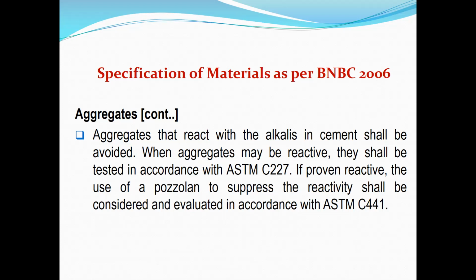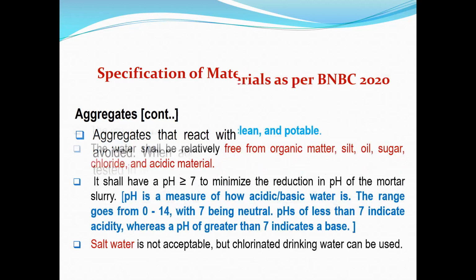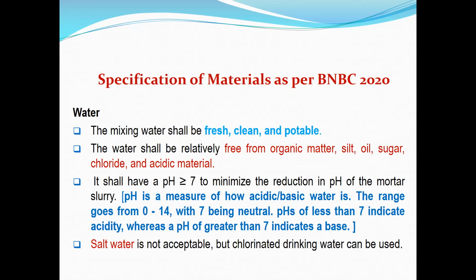So for ferrocement structures, what I want to say is that quality control is very, very important. It's not that you take cement and then place it over the wire mesh. Here the choosing of the cement, the type of aggregates, and the aggregate properties should follow the ASTM standards. Otherwise, you will not get the standard for ferrocement structures, because this requires very fine care in the selection of materials.